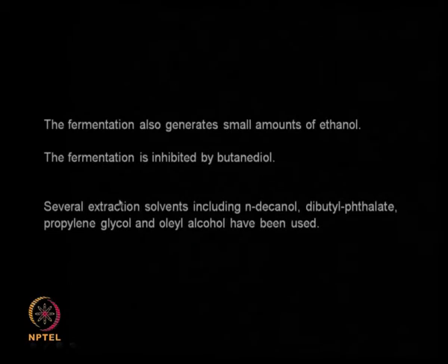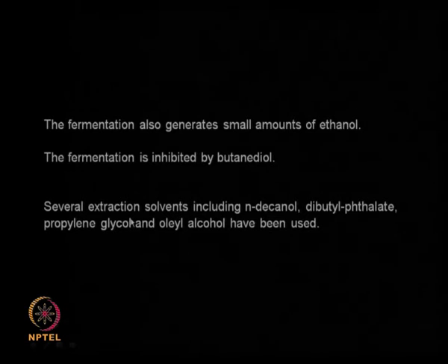Number 2, butanediol itself is toxic to these organisms. So, what you have to do is, as soon as you produce butanediol, you have to remove the butanediol and then send the broth back into the reactor for further fermentation. So, extraction is part of the fermentation here.